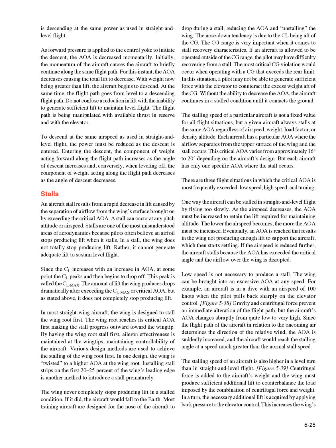To descend at the same airspeed as used in straight-and-level flight, the power must be reduced as the descent is entered. Entering the descent, the component of weight acting forward along the flight path increases as the angle of descent increases and, conversely, when leveling off, the component of weight acting along the flight path decreases as the angle of descent decreases.